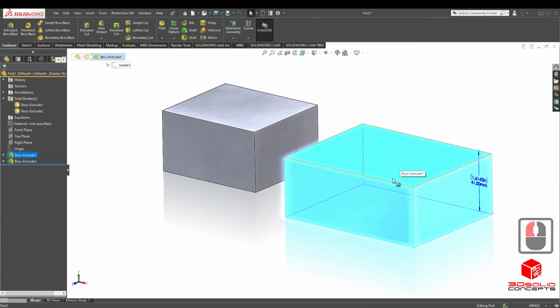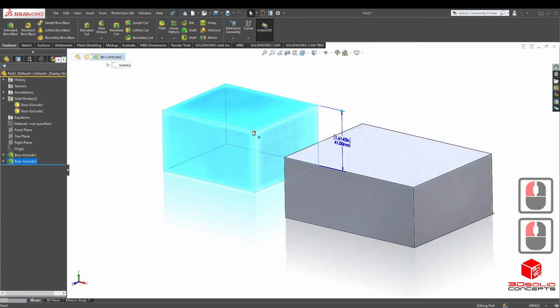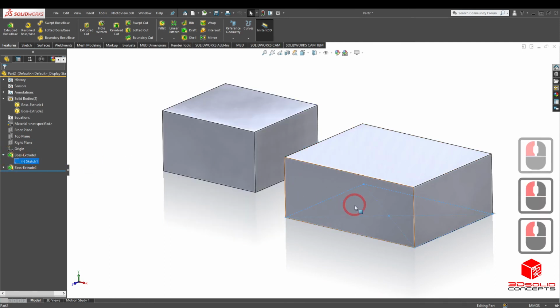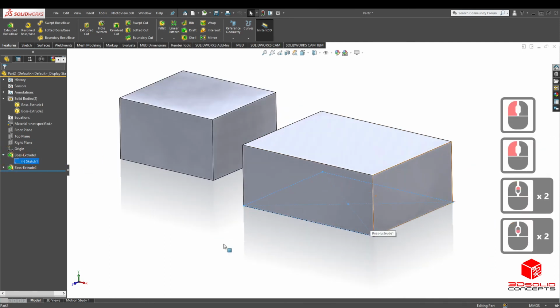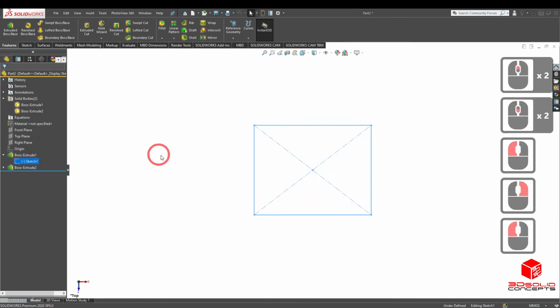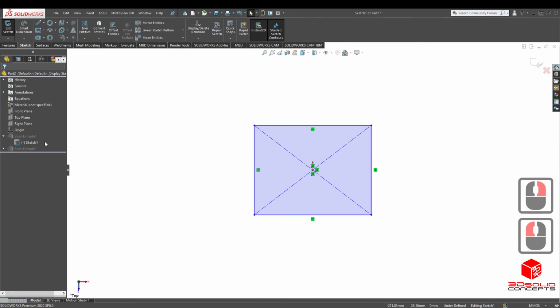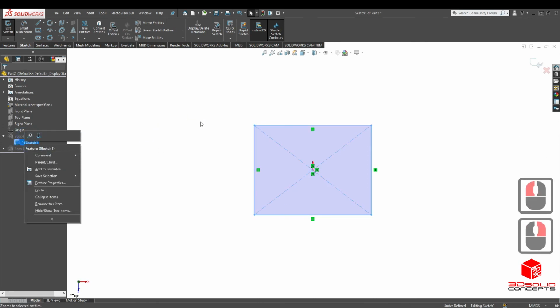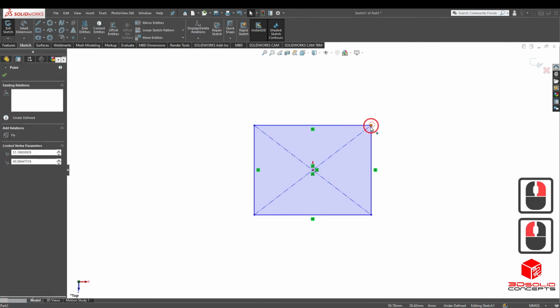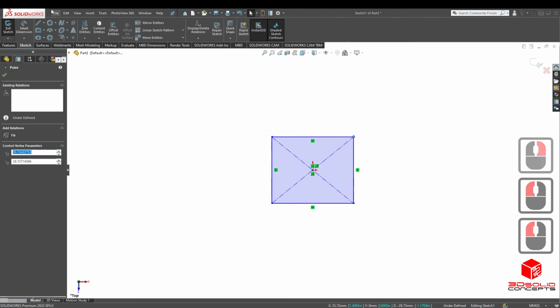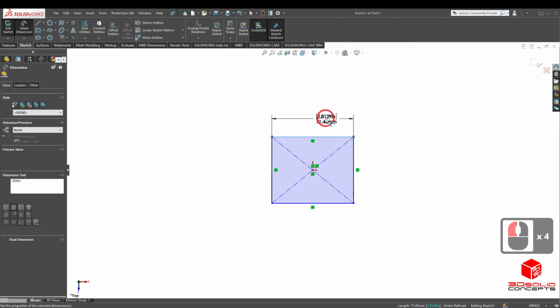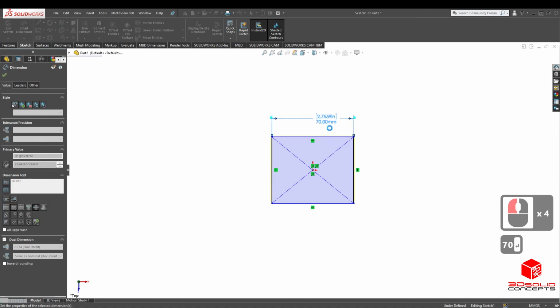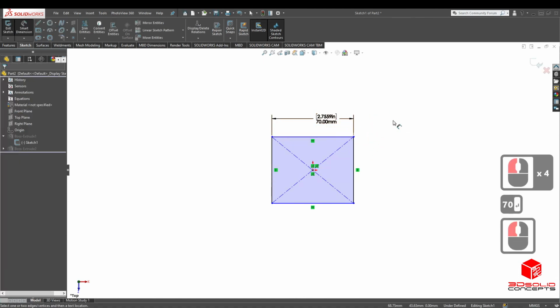As you see, we first created our first extrude, and then we created our second extrude. And if you click on this arrow, you get our previous sketch. The wonderful thing about SolidWorks is that you're able to manipulate the sketches relatively easily. If I right click and then edit sketch, I'm able to move around my sketch or change or add dimensions. Let's say we call this 70.